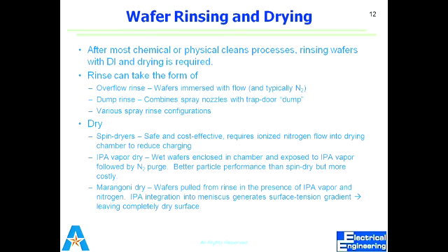Why do we call it dump rinse? As the name shows, the bottom of that chamber is actually a fake bottom, because when it fills up, that bottom is removed and all the water is dumped to the drainage, and again it starts putting in new water.